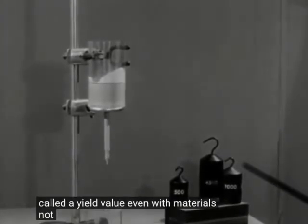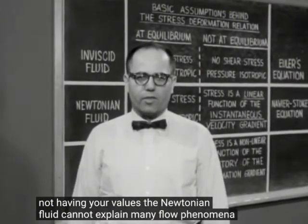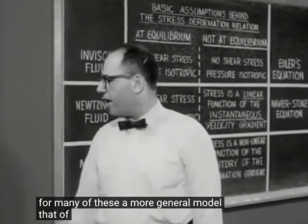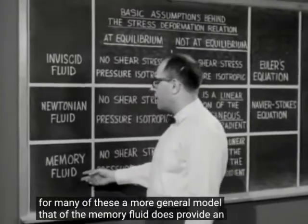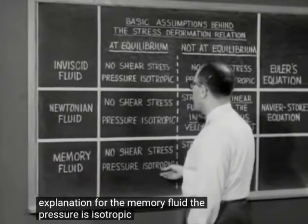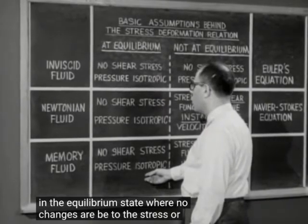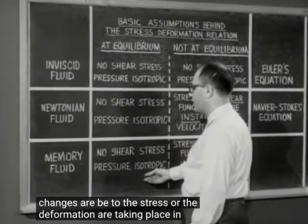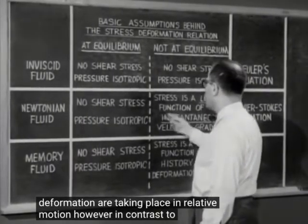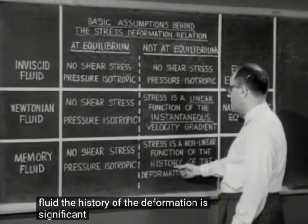Even with materials not having yield values, the Newtonian fluid cannot explain many flow phenomena. For many of these, a more general model, that of the memory fluid, does provide an explanation. For the memory fluid, the pressure is isotropic in the equilibrium state where no changes of either the stress or the deformation are taking place. In relative motion, however, in contrast to the Newtonian fluid, the history of the deformation is significant.